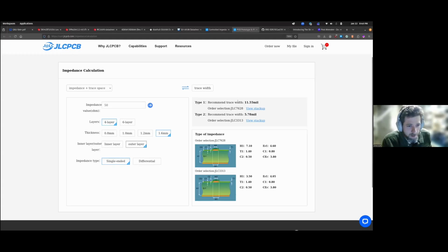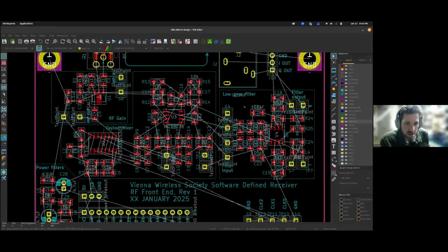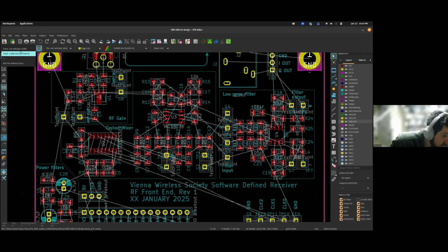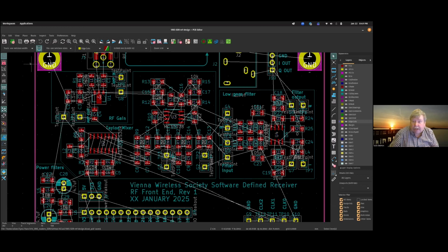I don't know why this is the bane of my existence, that you have millimeters, which is metric units, and you have mils, which is not metric. It's not millionths, it's thousandths of an inch. If anyone knows why mils are called mils and not thous in the PCB world, I would love to hear that. But long story short, if you convert that into sensible metric units, it's 0.368 millimeters. So I previously calculated that. It's an English thing. There's no magic as to why they do it. It's just metric versus imperial.